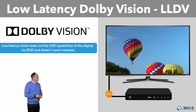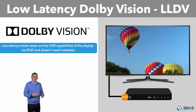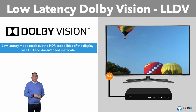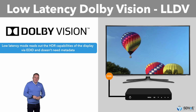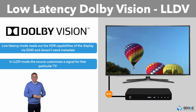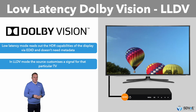In short, with LLDV, the processing is done at the source, eliminating all problems associated with the high latencies and the transfer of dynamic or static metadata, which is not sent to the sink in LLDV. In standard mode, the metadata is used by the display to tailor the video signal to match the display's specific capability for brightness.